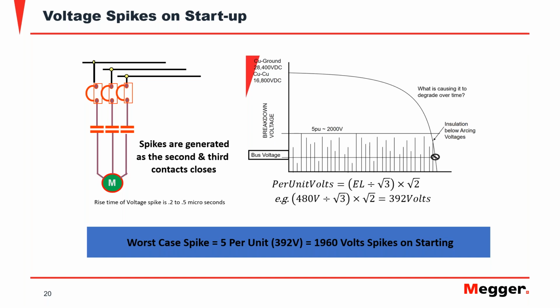But when the machine starts, when the machine is put in service, when the machine is connected to the system, there is a transient process where the machine draws an amount of current that is sometimes up to 7 times the nominal current of the machine.